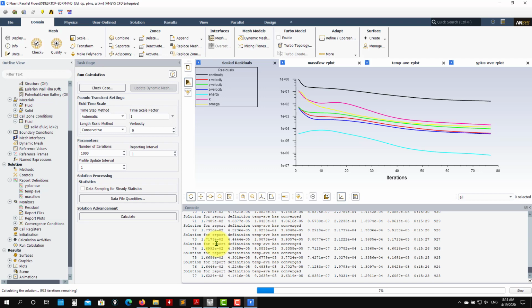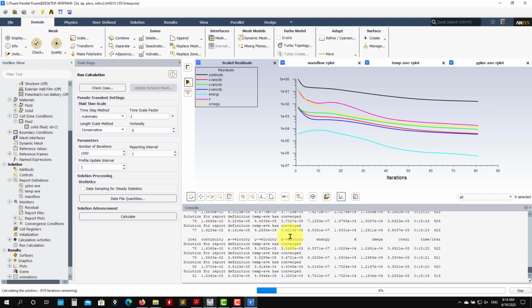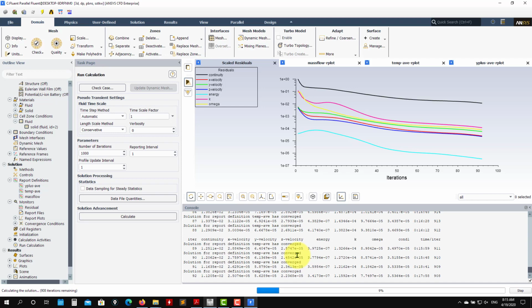Okay, see that in my case the condition that we put is already converged, after probably 60 iterations, but still the residuals, they haven't converged. So remember, you need to fulfill both of them: the residuals and those conditions that are put in there.